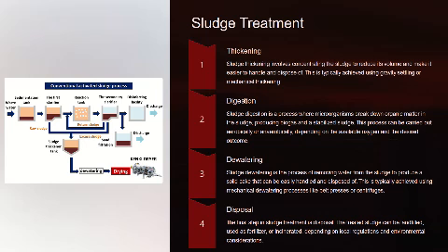The treated sludge can be landfilled, used as fertilizer, or incinerated, depending on the type of regulations that exist in the place. Some places might want to protect the environment so highly because of very, very good reasons, so you cannot do certain things like incineration. You would have to use it as fertilizer. So depending on the type of place you find yourself in, you tune your disposal technique to it.